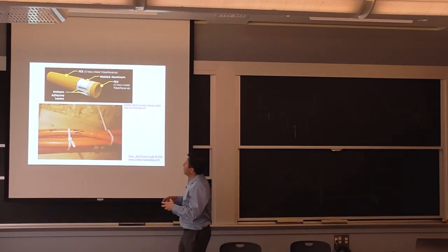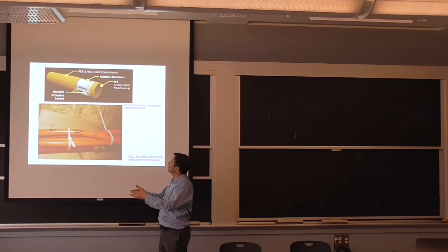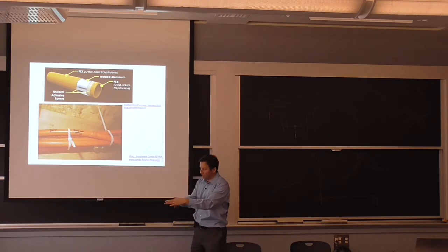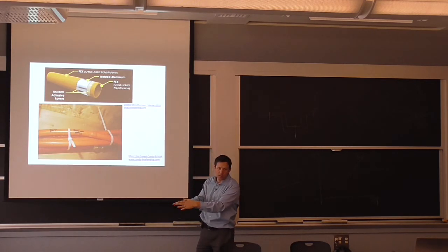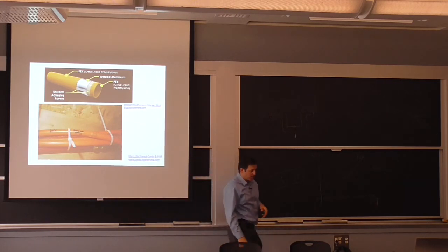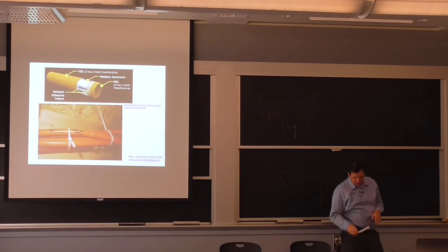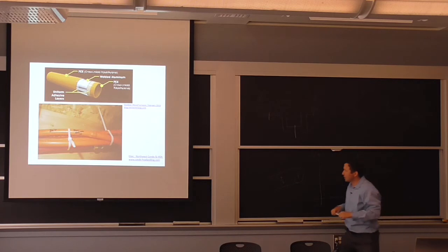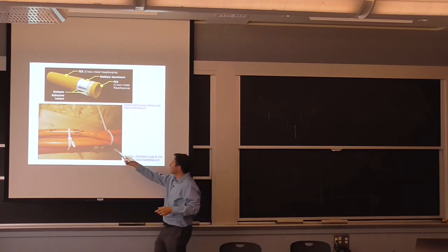But it can all be done as part of a single extrusion, a multiple extrusion process where you have the polymer coming in to make up the inside. You have the aluminum foil that gets overlaid and welded. So you have a little lap there on the aluminum layer, and then you put adhesive, you put the outside layer. In service, we've seen a lot of failure of these, and it's interesting because what happens is you fail the aluminum layer before it starts bursting. You can see a burst here on the outside.